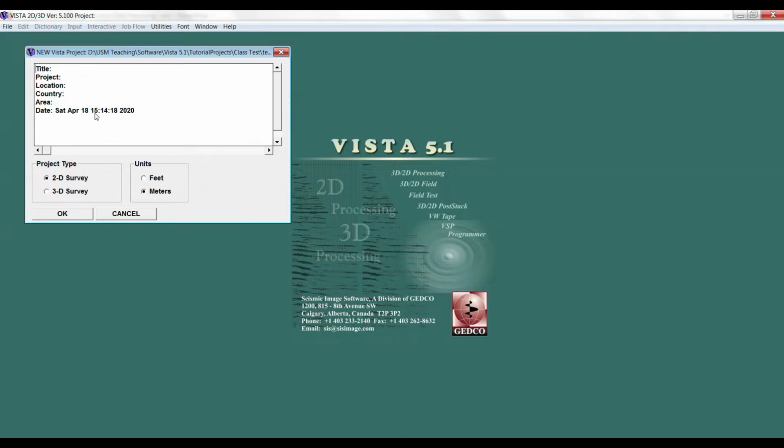You can say save. Now you have to define the title of the project. The project title is processing lab. The project is 20 short line. Location is Malaysia, the country, or you can define the name, area offshore. The date will be defined like this. Now you can choose the project type: is it a 2D survey or 3D survey, and what type of unit you want to use in the acquisition and processing. We're using a 2D survey and the unit will be in meter.